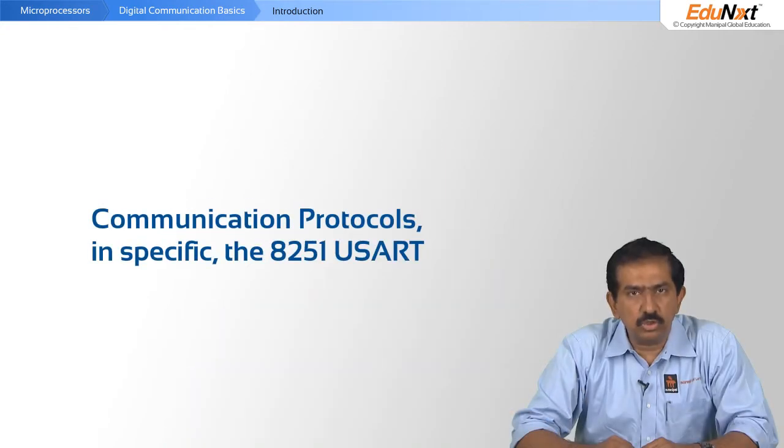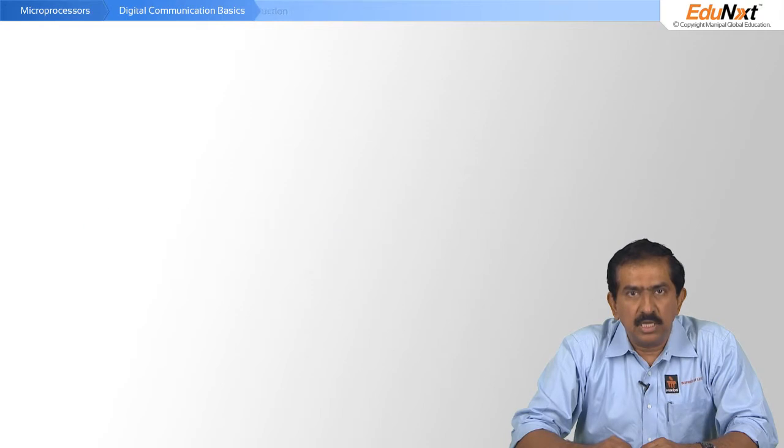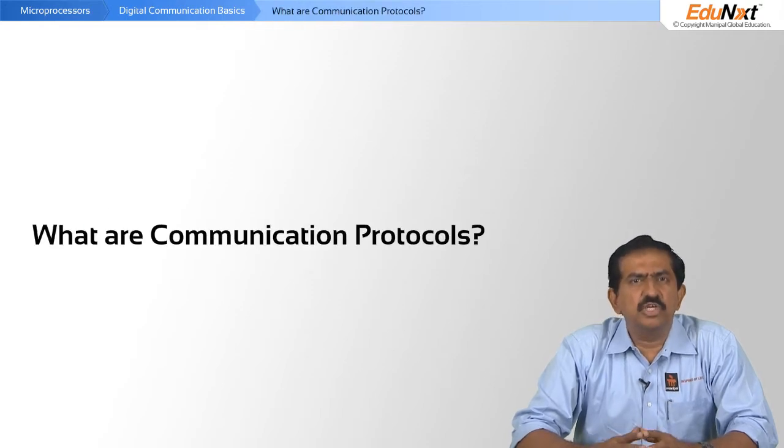Hello and welcome back. In our last video, we were discussing the programmable interrupt timer. And in this video, I'm going to take you through communication protocols and, in specific, the 8251 UART. First of all, what are communication protocols?